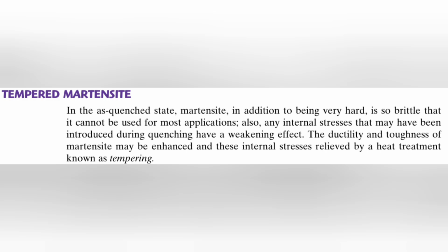So we know martensite is harder, right? We already discussed the factors influencing the formation of martensite. We already discussed the more the presence of carbon content, it would really affect the hardness, or it would become more hard. Yeah, it would obviously become harder, but on the other hand, it will become brittle. So you cannot use it for any other purpose.